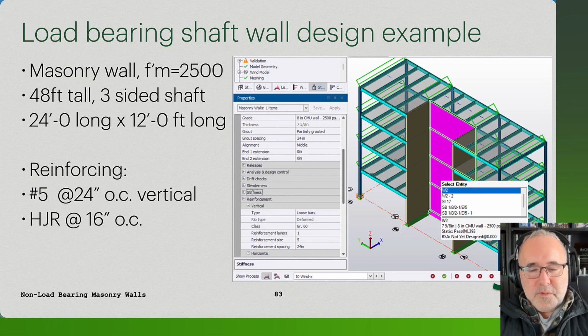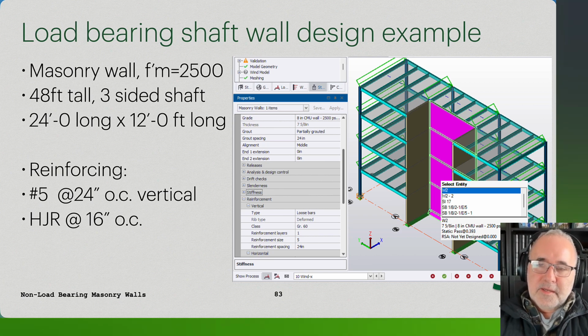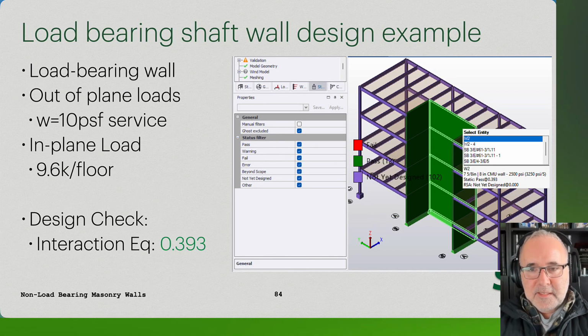We can look at the overall stiffness of this element, and the overall forces and in-plane shear forces developed on these floors and assigned to the rigid diaphragms at each level. For that, I can look at the overall capacities of each of the different wall panels. Each floor would have a different capacity. Certainly, I could change the reinforcement at each floor and look at optimizing the overall capacity for this wall design.